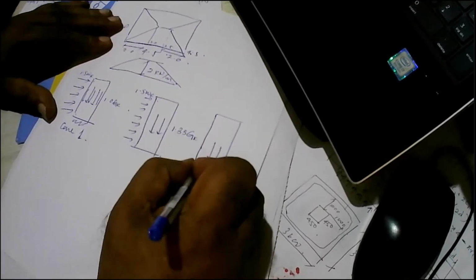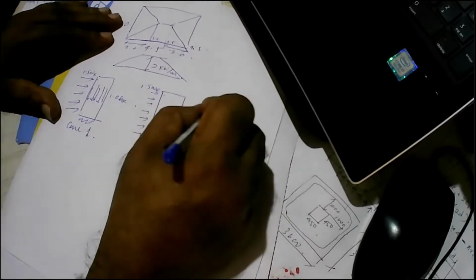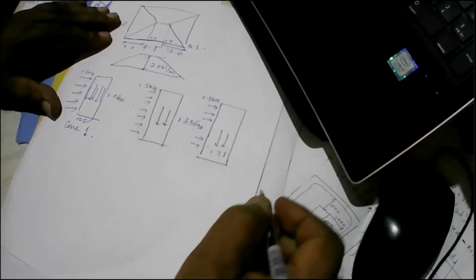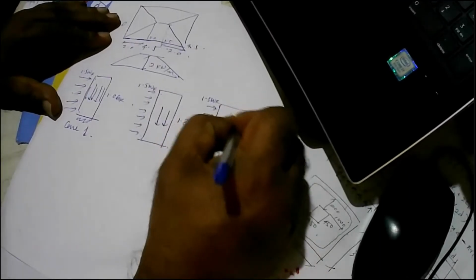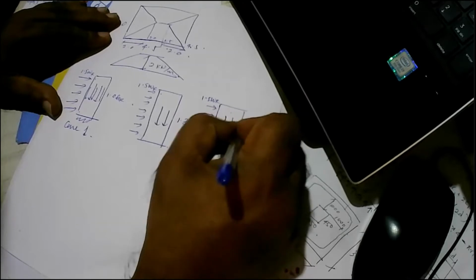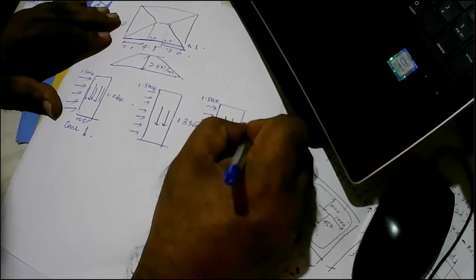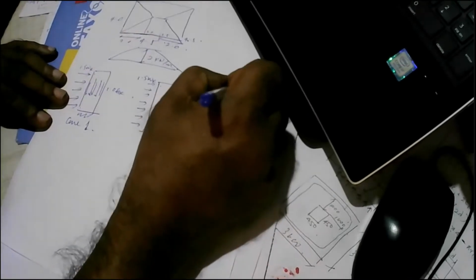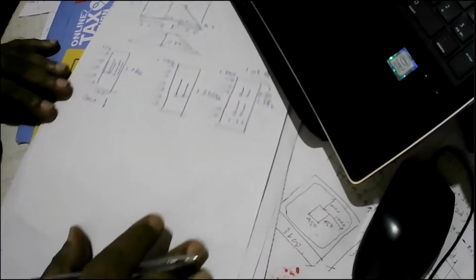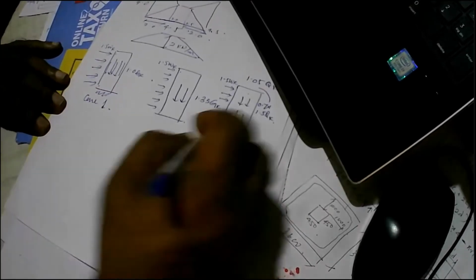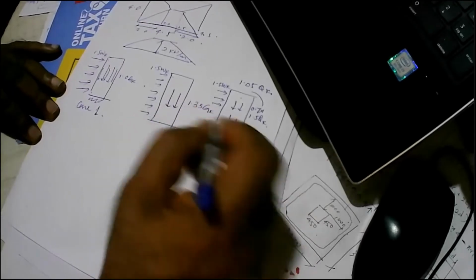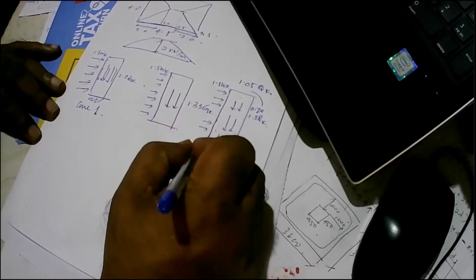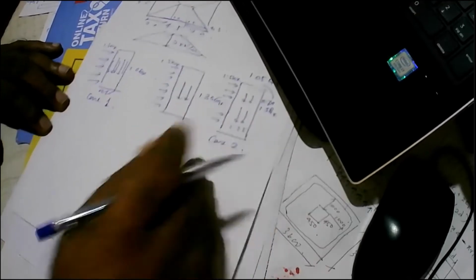All these loads 1.35 and this way 1.5 WK. But in addition to that, we can get 0.7 times 1.5 times QK. That is the imposed loads also acting. And this gives a value of 1.05 times. And we say this case 1. And if you look at these two cases, you can see this is going to be more critical. So no need to worry about this particular case. So we can say this case 2.